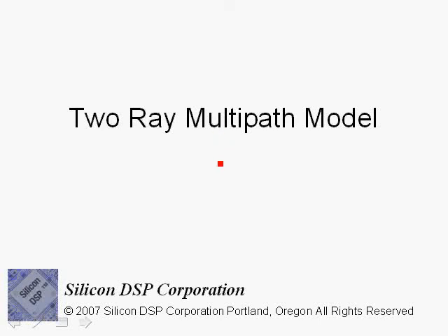We begin the overall discussion on multipath fading channels by introducing the two-ray multipath model, which forms the basis for understanding many of the multipath phenomena that we encounter, including periodic deep fades and the depth of the deep fades, and also the spacing between the deep fades that are all related to the multipath delay, and also the amount of attenuation of the reflected multipath in a two-ray model. So in this section we will go ahead and derive some formulas that go a long way towards explaining what is going on in a two-ray multipath model.